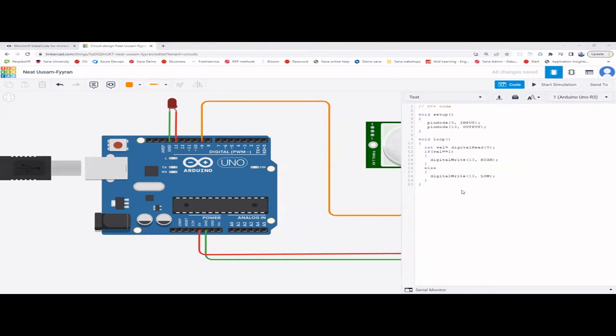The output pin is a bit different in the Sinhala and English books. Here it's 9, but your textbook just shows pin mode 8. So you have to change either the circuit or the code, at least one. In the Sinhala book it's 8 in both places, but in English there's a small printing mistake.